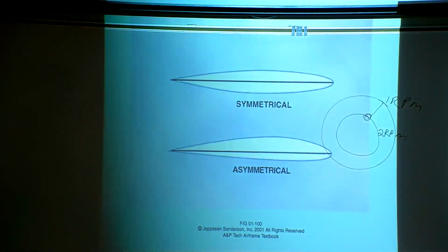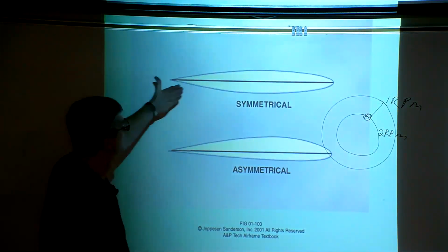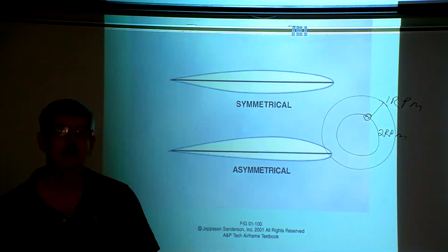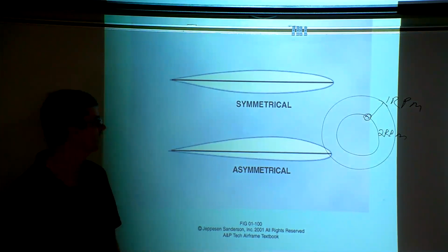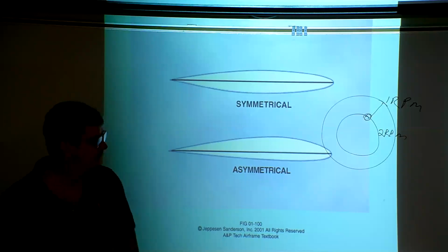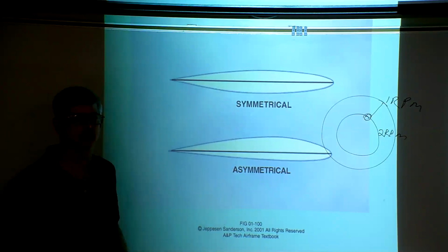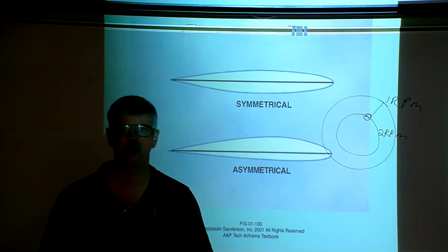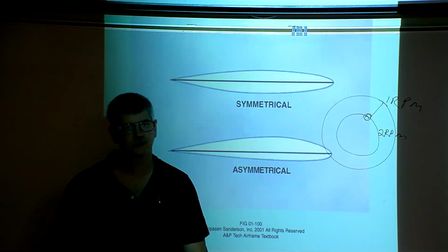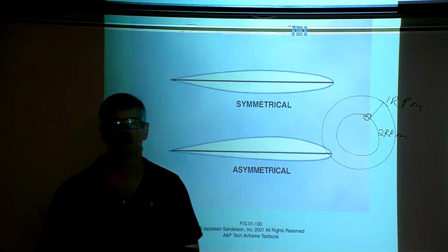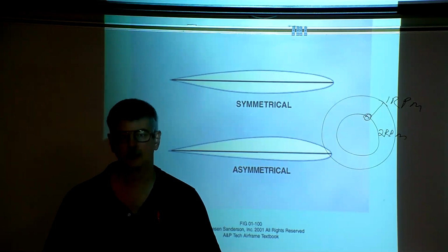Helicopter rotor blades are generally of the symmetrical shape. The reason for this is that it puts less strain or vibration within the rotor blades. With a symmetrical airfoil, when the angle of attack changes, the center of pressure or lift does not change very much. We can say that it doesn't change. Therefore, it does not put any additional twisting force on the rotor blade.